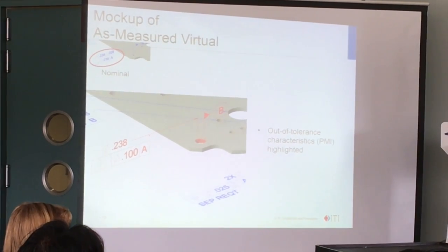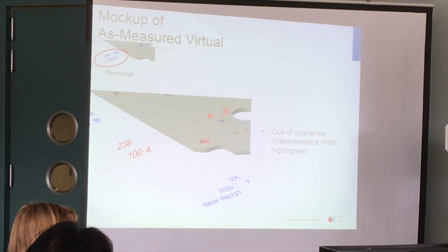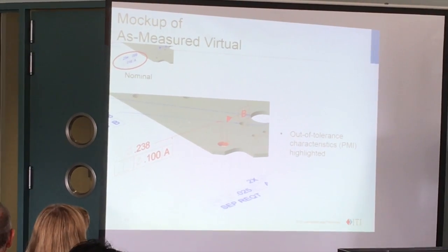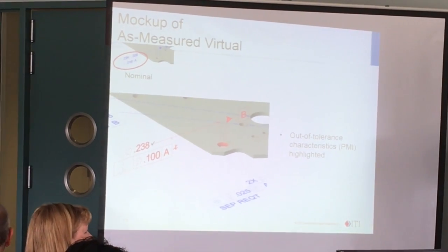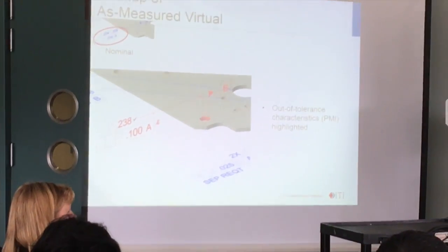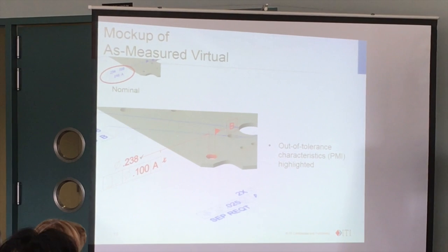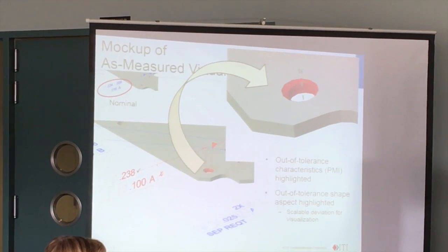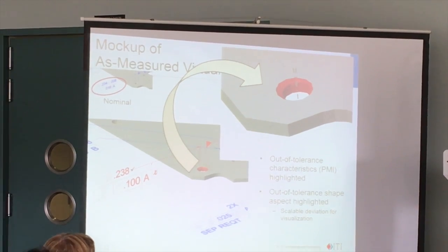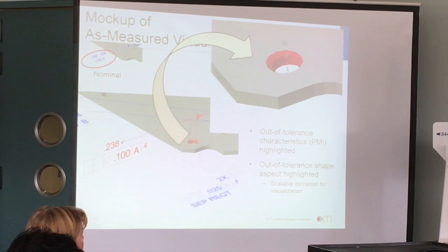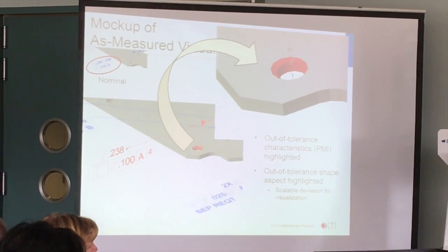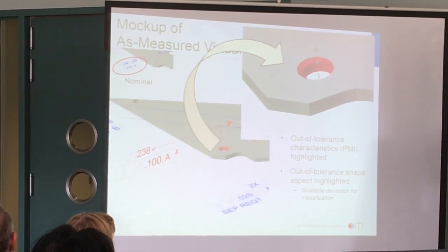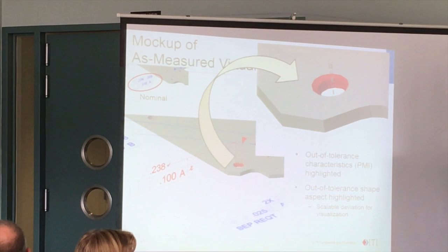You see in the upper left-hand corner the nominal PMI data content coming downstream, and then in the low center you see the as-measured results. The as-measured results could be a pass, a checkbox on a piece of PMI that was within the bounds of the nominal, or the one that was flagged as being a failed operation. Also, you note the notion of being able to take the point cloud information, the touch point information, develop a tessellated representation for that particular area, and then be able to superimpose that on the design and provide feedback in a visual way for users.